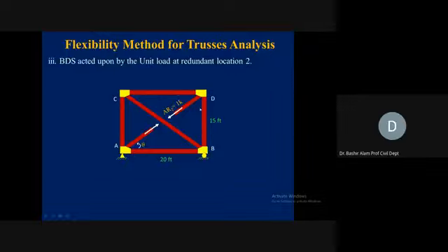Its vertical component was downward, so at D, the member BD force will be towards up direction, means to balance this downward. So against towards the joint and towards the joint means FBD, it is in compression. You can resolve this into rectangular components. So horizontal component will become member CD force and vertical component will become member BD force. Similarly, here you can find out the member AB and CD. It is the same force we are resolving here in the rectangular components, and we can find their directions.